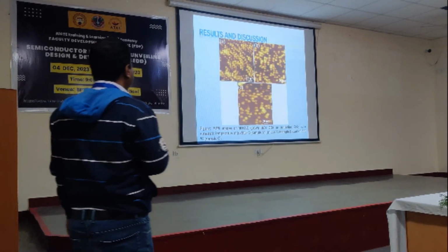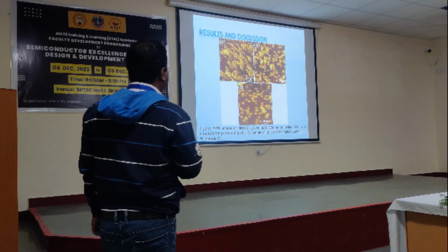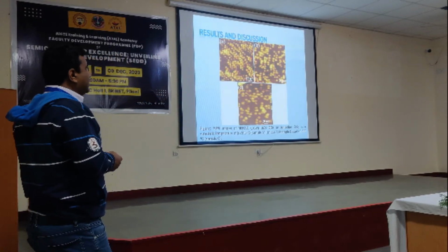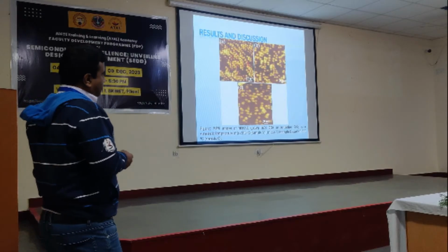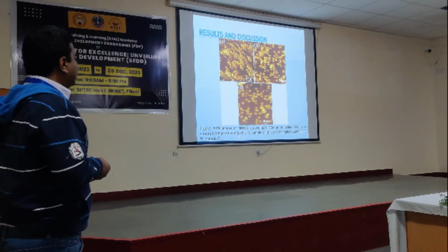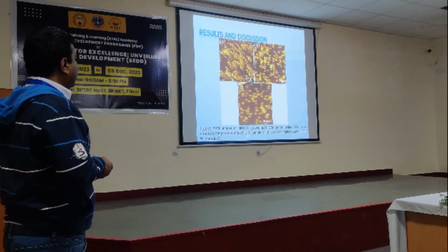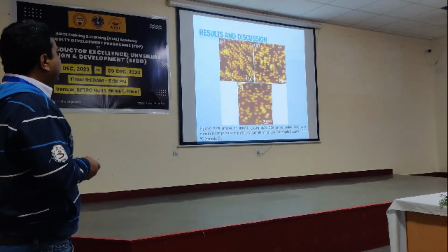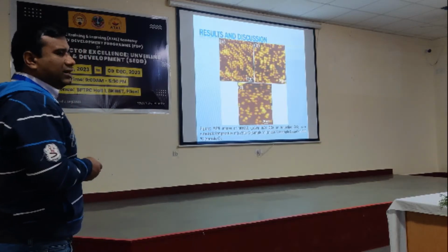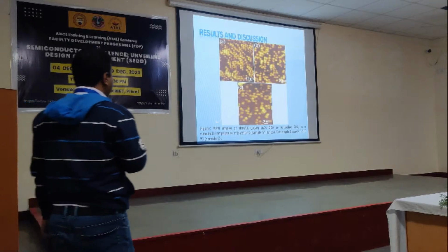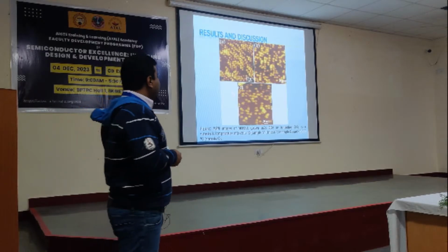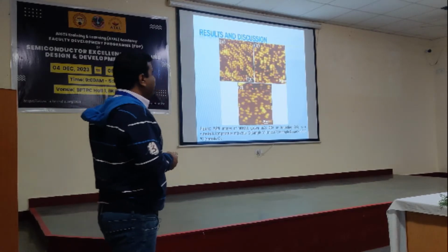Now these are the AFM images of the indium arsenide quantum dot grown on a dielectric material. This is not on gallium arsenide. This is the formation of indium arsenide quantum dot on a dielectric, that is ZrO2. You can see 500°, 550° and 580° centigrade. Because you are growing the material on a dielectric, it will follow the Volmer-Weber growth mode. In previous cases it followed the Stranski-Krastanov growth mode.